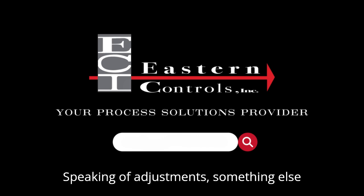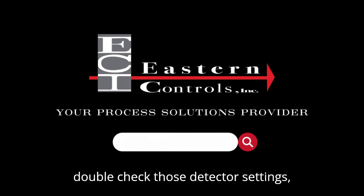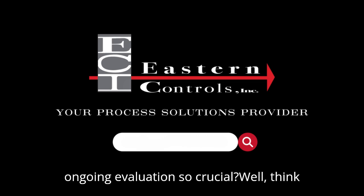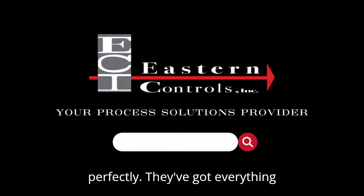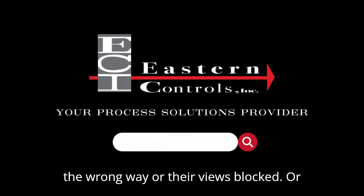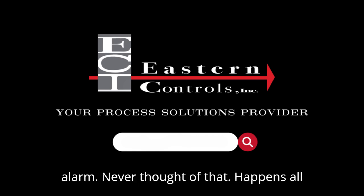Exactly. And speaking of adjustments, something else that came up was how important it is to double check those detector settings, those coverage maps, after any changes are made at a site. Why is that ongoing evaluation so crucial? Well, think about it. You've gone through all the trouble of positioning these detectors perfectly. They've got everything covered. But then they add a new production line, move a storage tank. Suddenly your detectors might be pointing the wrong way or their view's blocked. Or even just a small change, like a new shiny surface that reflects light, and boom, false alarm. Never thought of that.